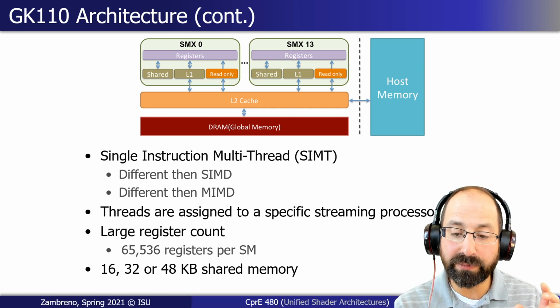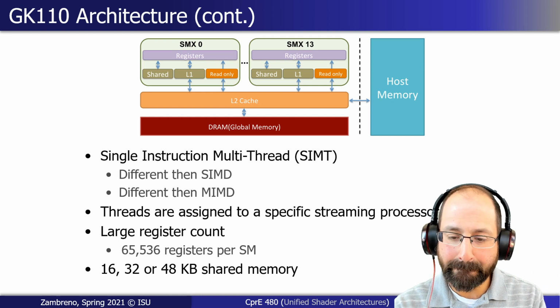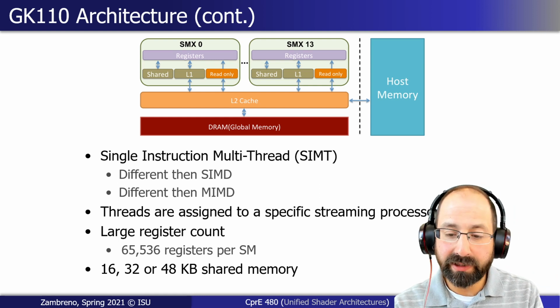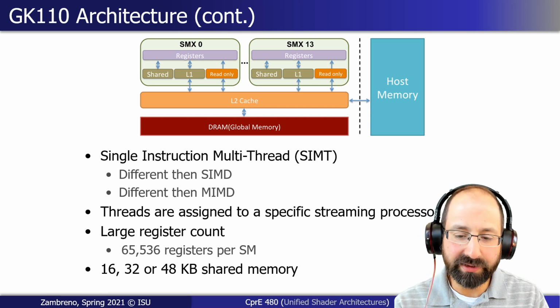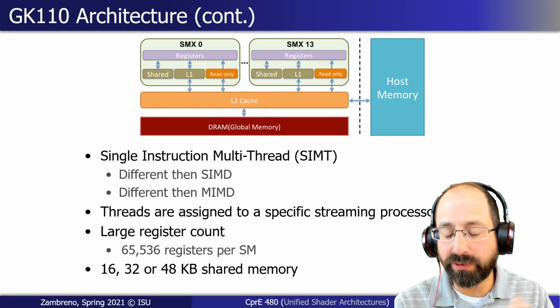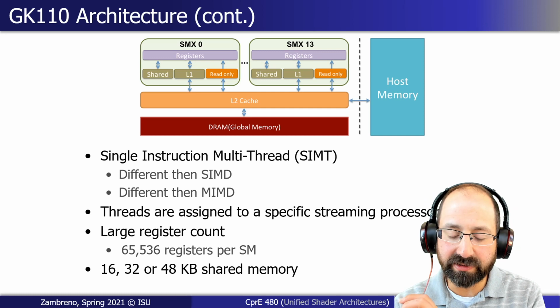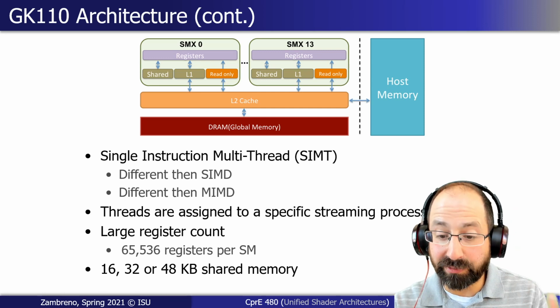So when it comes time to go from one thread to the next thread in this SIMT model, the context switch is no more than just saying, you're next. The functional units are yours to do what you need to do. Your registers are there. The next thread's registers are next to yours, and they're allowed to share.